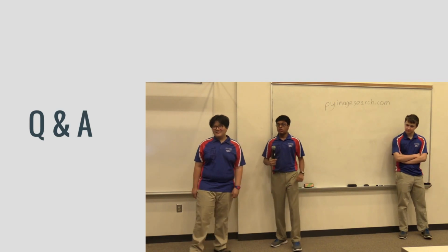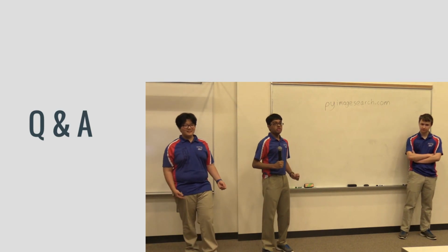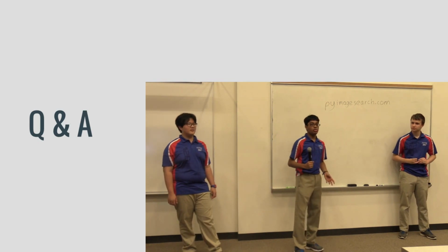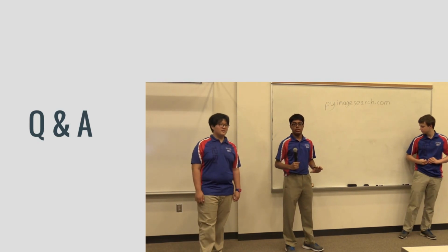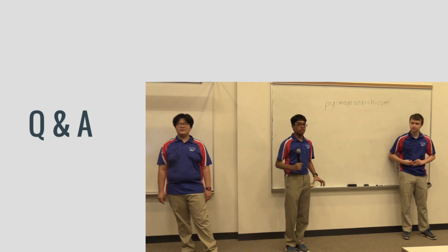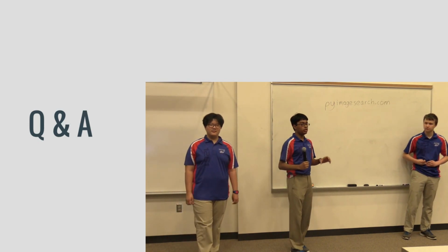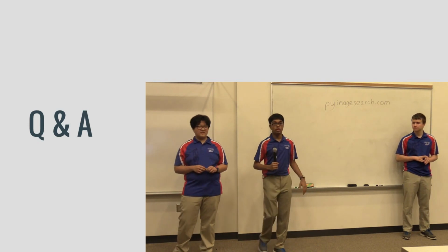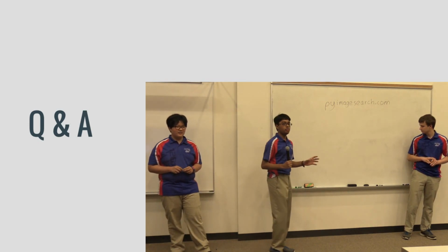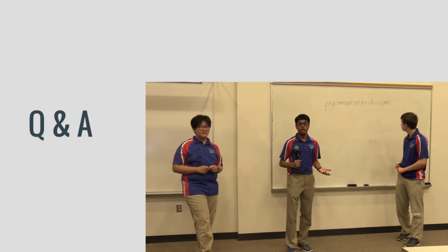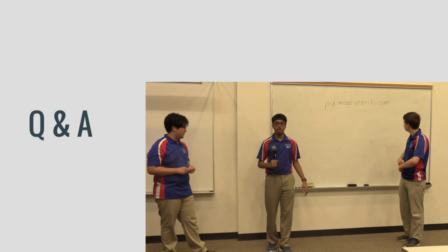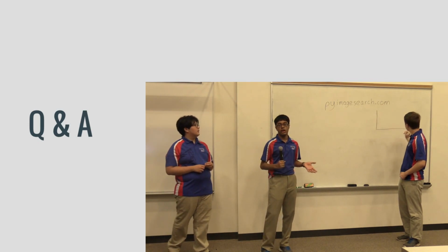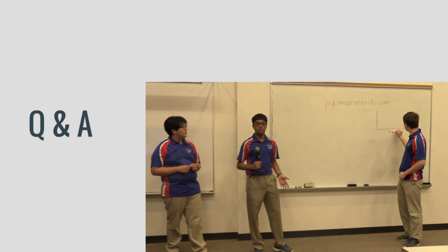It's what we use to target our motors. On our shooter, we don't have a servo or anything that can precisely set the angle on something like a shooter. So with PID, you give it an input that's based on an encoder, for example, that's attached to your shooter, and you put the PID output as your motor.